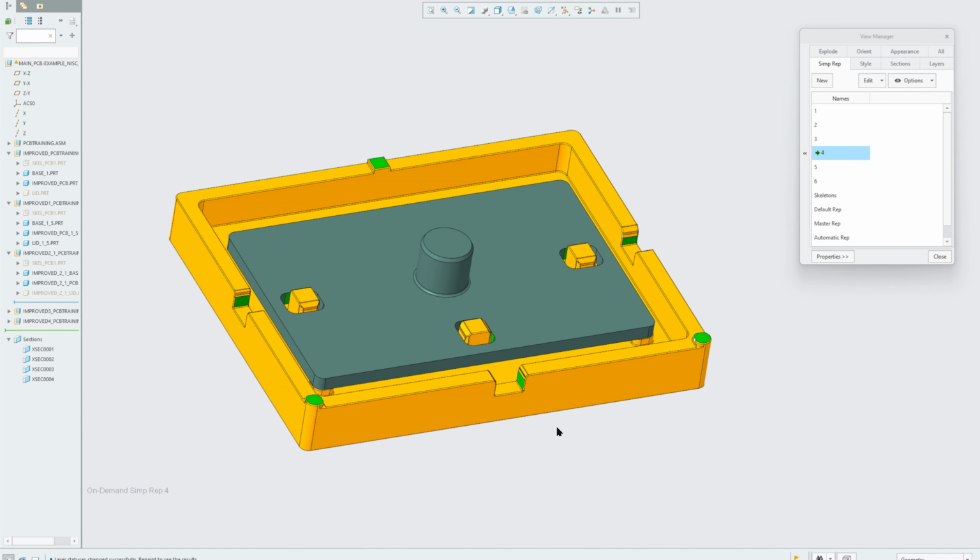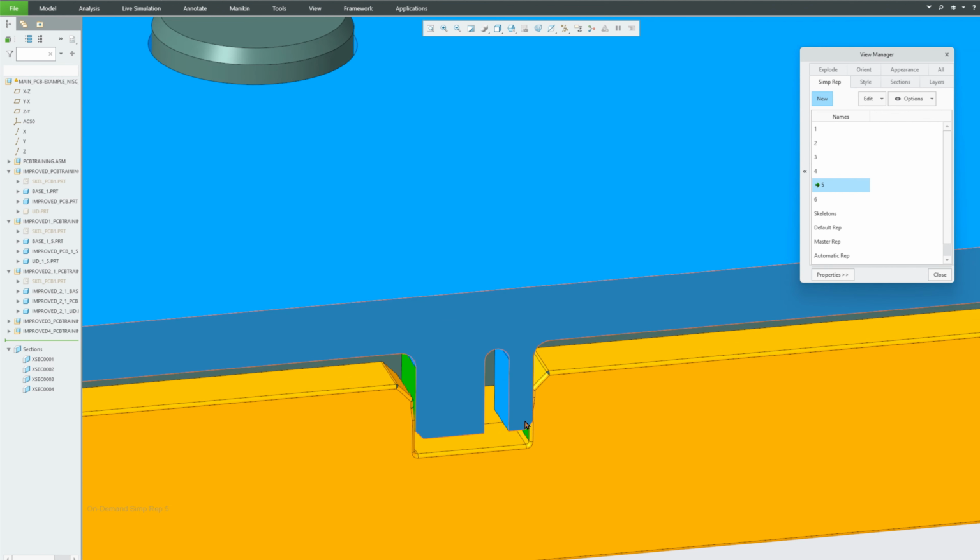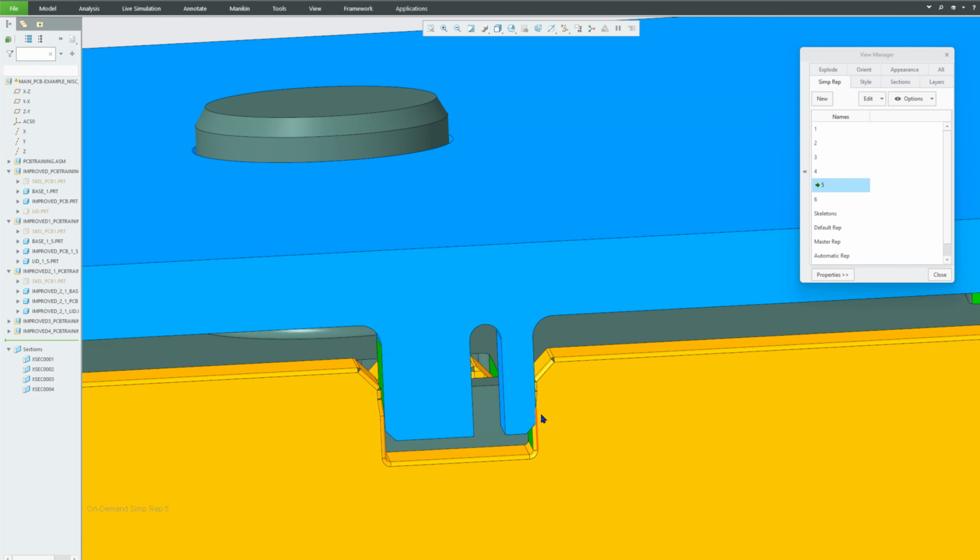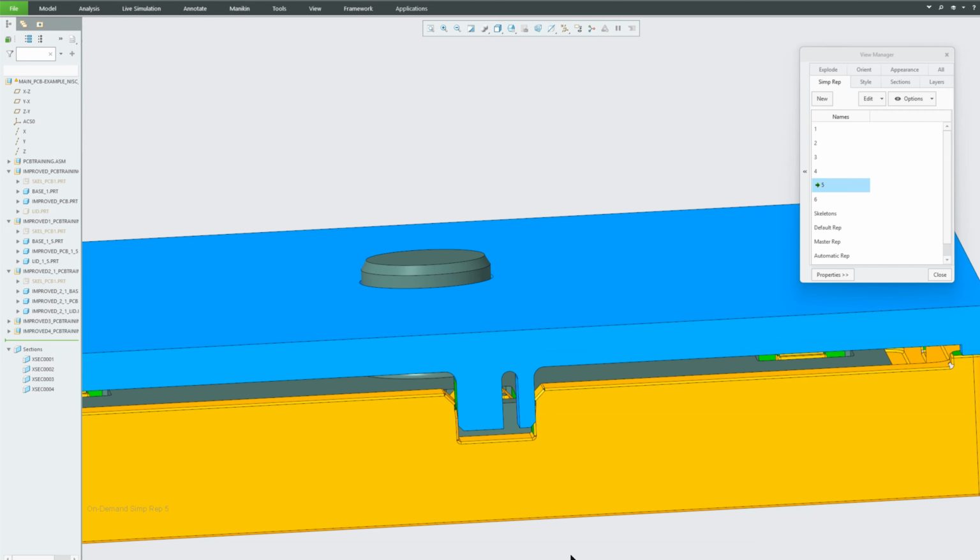All right. So what you will see here, when we're going from iteration number 4 to iteration number 5, is that we introduce these small cutouts, and we actually introduce a small overlap here in the geometry. So it's a small, like a compliant mechanism, or you can also call it a small feature with a little bit of flexibility that pushes the lid to the left side in this view.